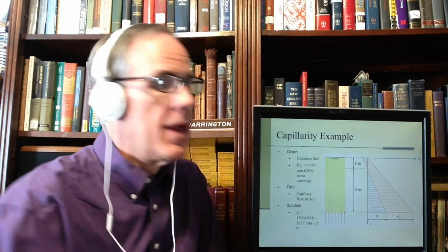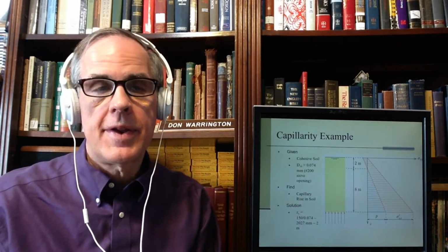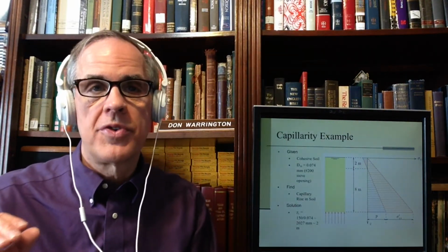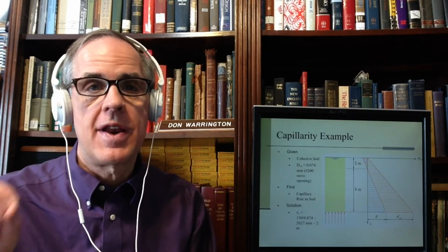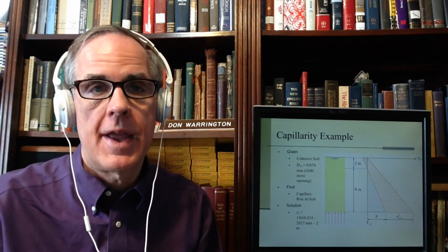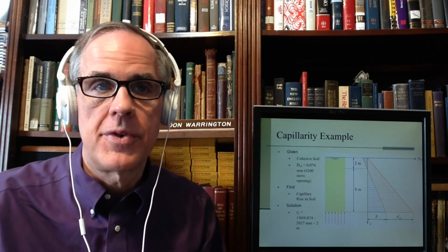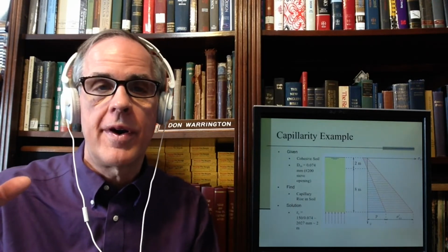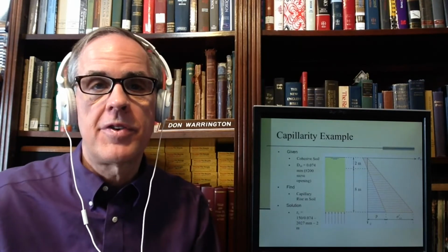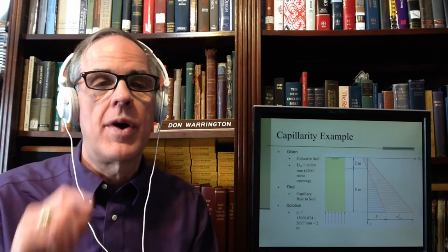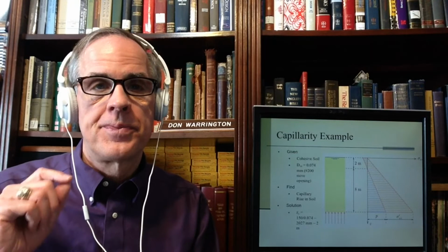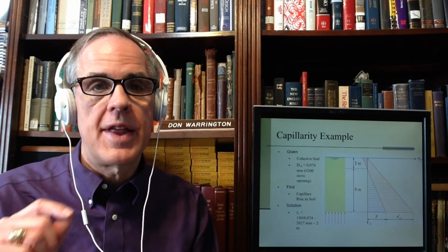But basically what happens is that the soils are actually saturated above the water table by capillary rise. Because if you don't have saturated soils, the tubes aren't full of water. So they are saturated. That's one reason why I define the water table as I do.